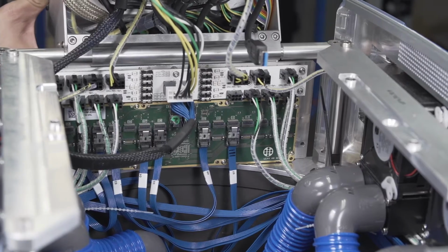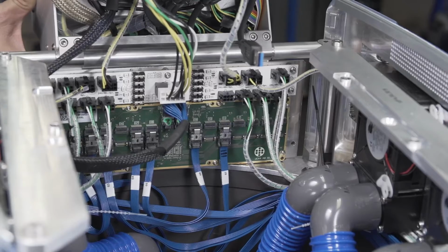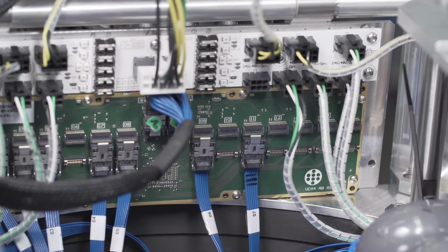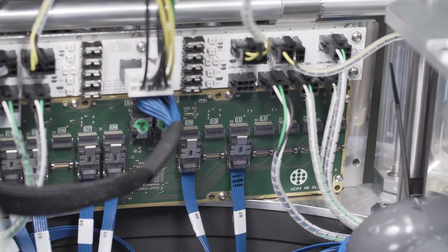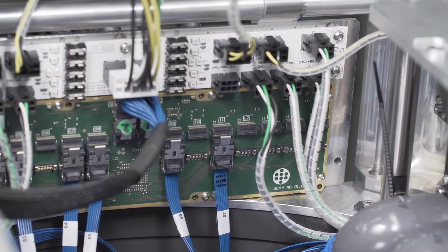The combination of the wide footprint along with this very fast frame rate allows a huge flexibility for the flight missions. You can either leverage this fast frame rate by flying super fast, which increases your collection efficiency, or you can use this fast frame rate to increase your forward overlap, and that has a benefit in your AT, and especially in the downstream processing of 3D products like the point cloud, surface model, terrain model by the dense matching technology.